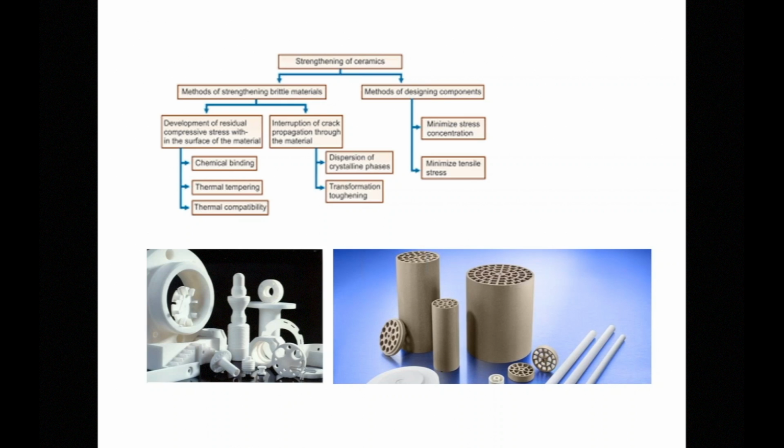So unlike metals, in which you can have domain and grain boundaries that can be controlled based on the annealing methods, here you basically have fusion properties. And a lot of the high temperature curing, which I will not have time to cover here, occurs at very high temperatures. Sintering, that might be a term that you can use, which at that point, most metals and of course all polymers would have degraded already.